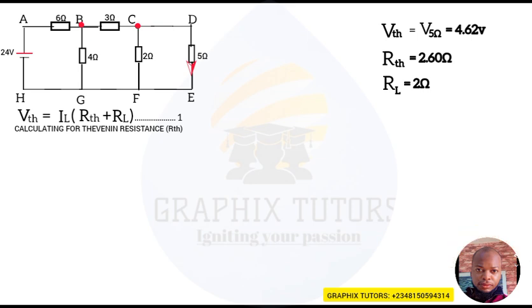So when we put all this into our formula, we say that my V_TH, which is giving us what we calculated for here, and that is 4.62, equals to the I_L, which we don't know, into bracket the R_TH, which is 2.6, plus the R_L, which is the investigating resistor, which is 2, right? And when we add two of them, we'll now be having my 4.62 equals to I_L multiplied by what?